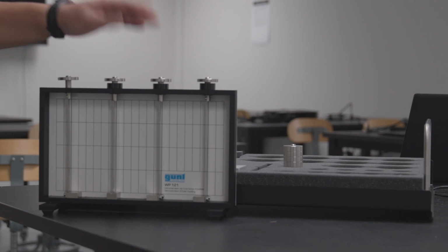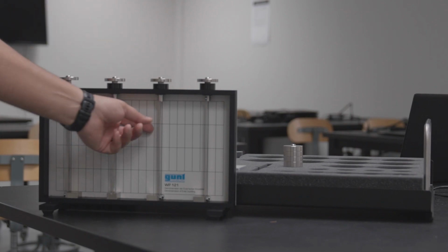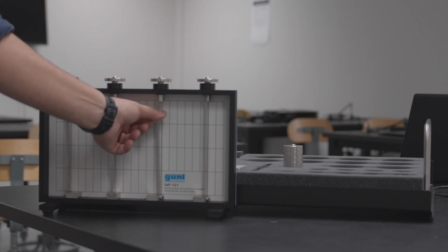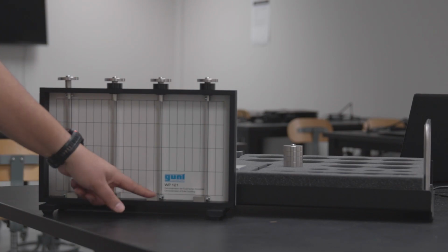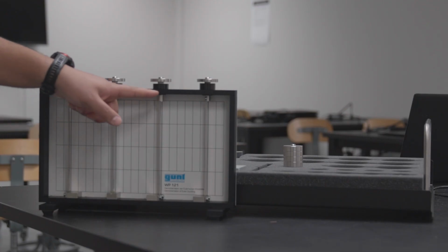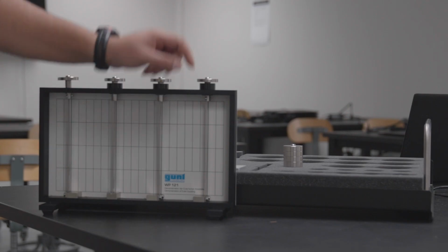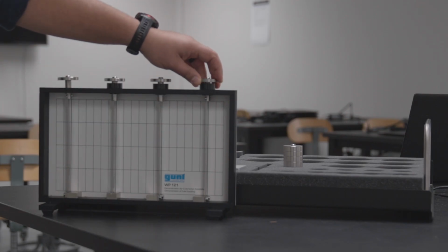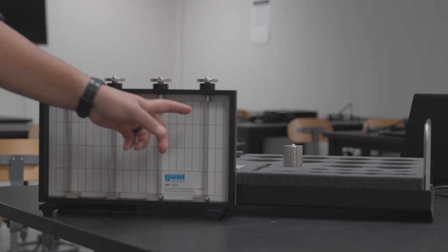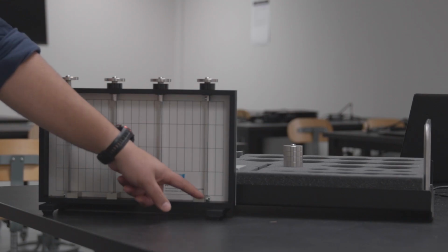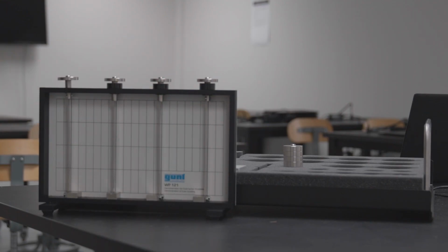And the third column has a pin support on top here, where we do see rotation, and a fixed support. So we have pinned, fixed, pinned, pinned, free, fixed, right? And the last one has 2 fixed supports. Closer to the supports, we don't really have rotation. We don't have any linear movement, any translation.